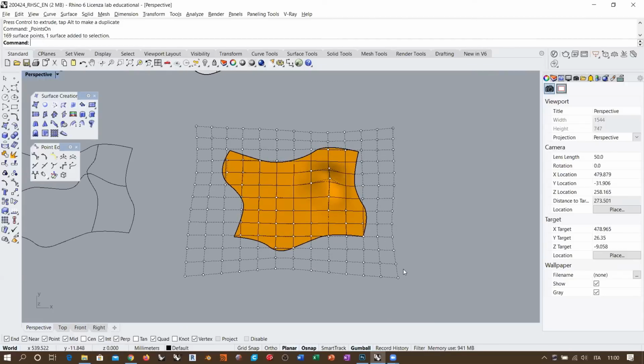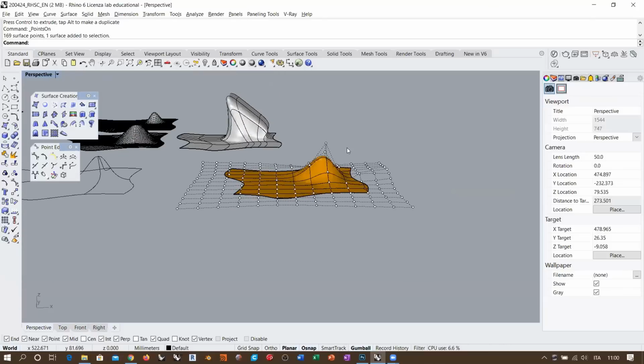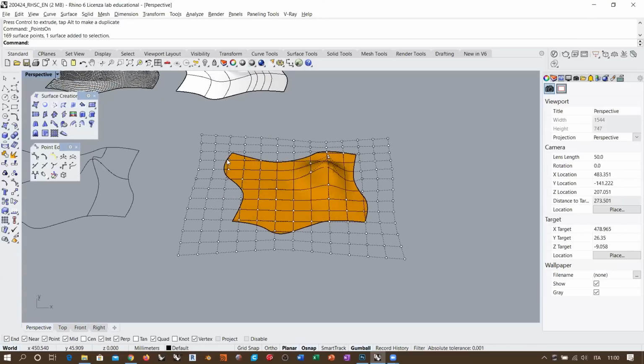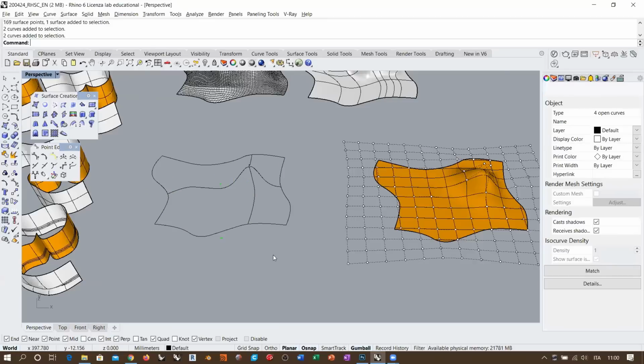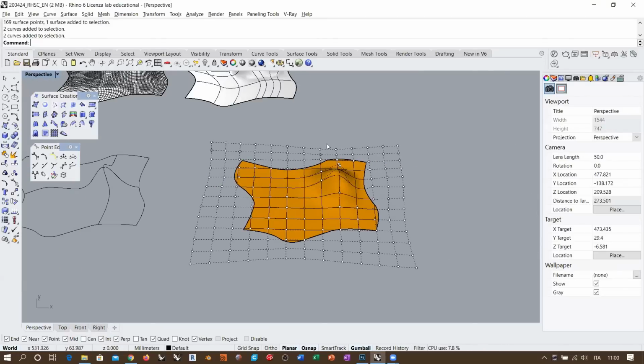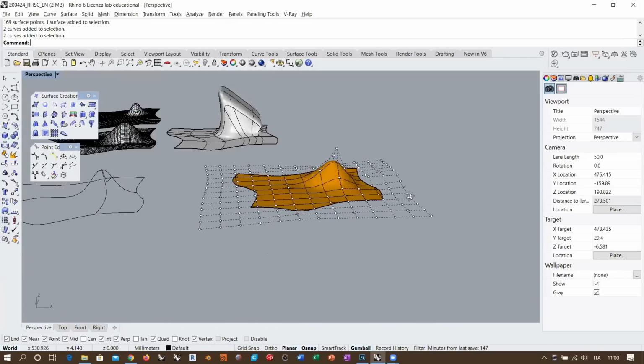But in general, this is a deformable rectangular surface that is deformed according to the input geometry you select, and then it is trimmed using the outer border you have selected. If you don't select an outer border which is closed, like in this case, the patch will only create this rectangular surface with the whole deformation that you can see here with this network of control points.